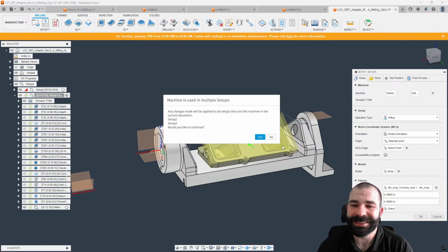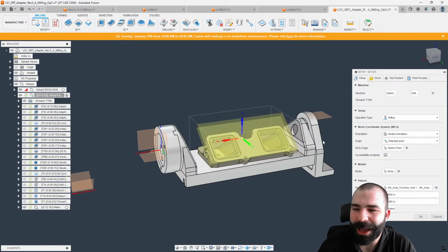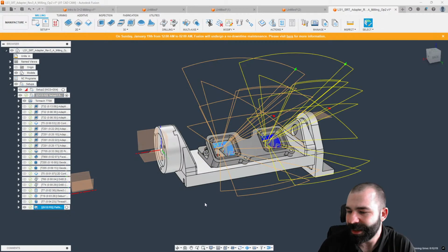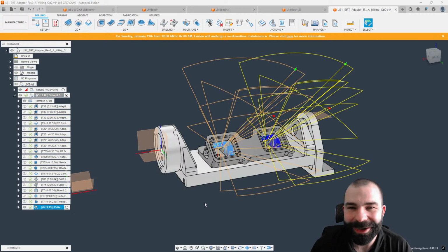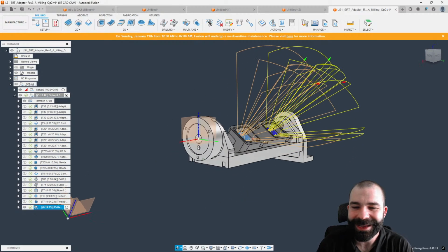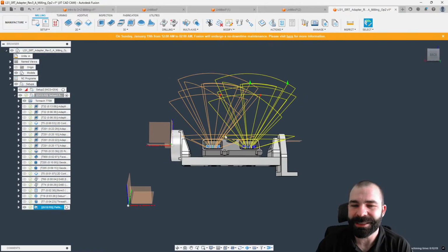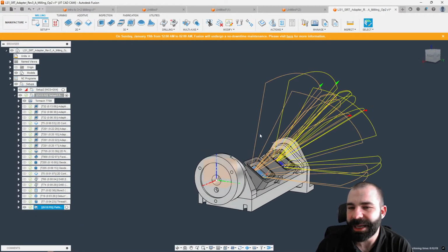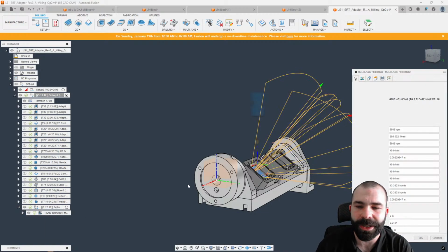So I've got to back myself up here real quick. What I wanted to show you guys is somebody had this dilemma. Hey, you have a 4-axis CNC mill in your garage. I mean, I don't know how many of us can say that. But the problem is my customer was getting Z over travels in simulation. So when you pay attention to your linking, guys, you have to make sure that your linking isn't exceeding your Z height in your machine. And it was a very simple fix once he saw the problem, right?